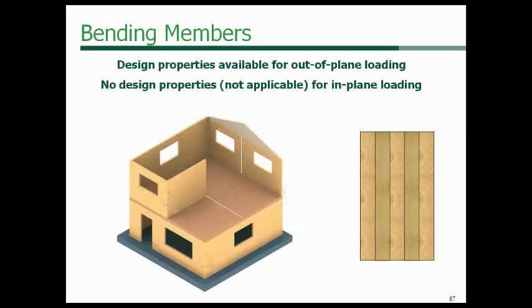One thing you will want to be aware of is that the manufacturing process doesn't apply any adhesive between the narrow face of the laminations, and there's not really any test data that's been performed on the application of load in that direction. So if you are using these in a lintel or header in a bearing wall, you will need to install additional framing. In bearing wall applications, these can be glulam, they can be LVL. You can use any type of header you would want.